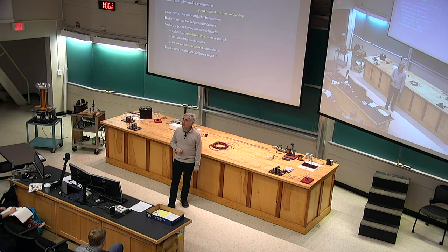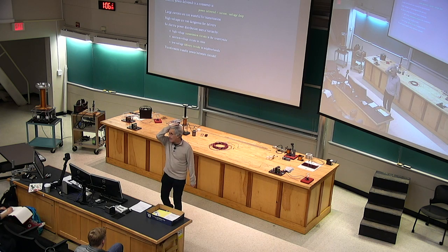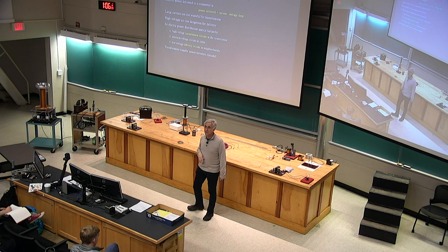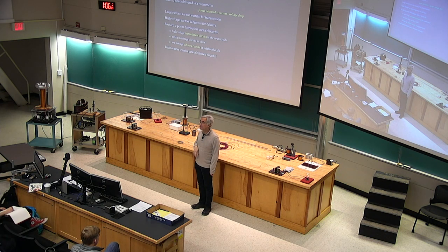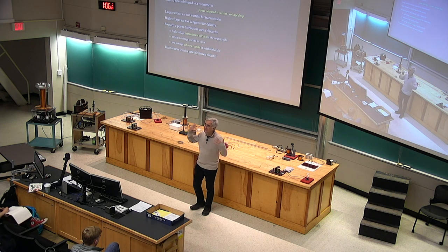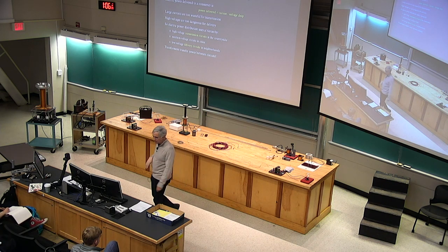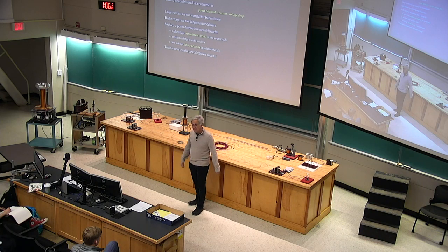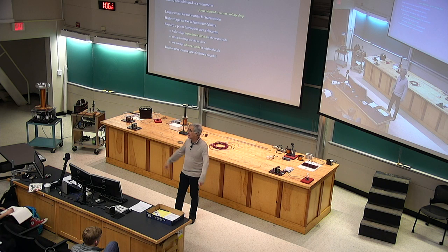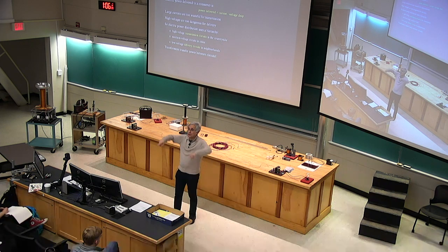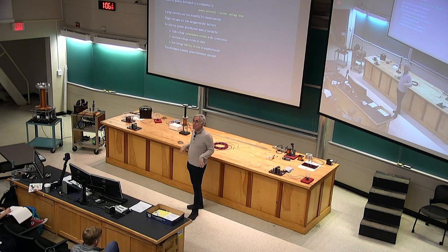Instead, the system that evolved uses a hierarchy of voltages, which is what this view graph's about. Power is transmitted long distances at high voltage with modest currents. So they're using that wonderful feature of electric circuits that if you drop the current, you can still send a lot of power, but you have to have big voltage drops. So transmit the power long distance at high voltage.